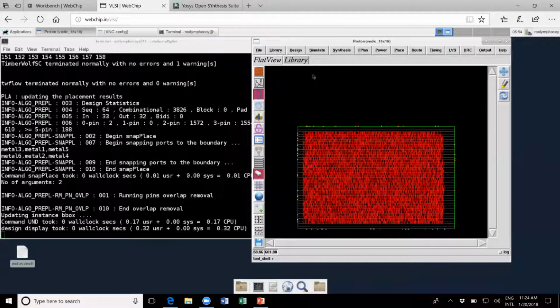If I can take that question. I think that NDR mostly refers to the clock tree. The idea behind that is when you're placing your flops, you want to make sure that your clock pin is accessible by a wide wire. So when we apply the NDR and the tool is trying to compute the congestion, it can make sure that congestion is computed with that wide wire assumed for the clock net.